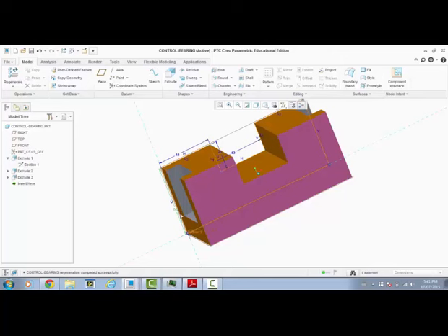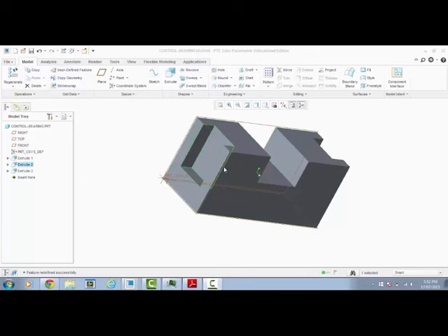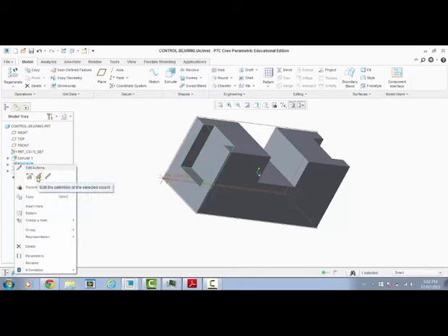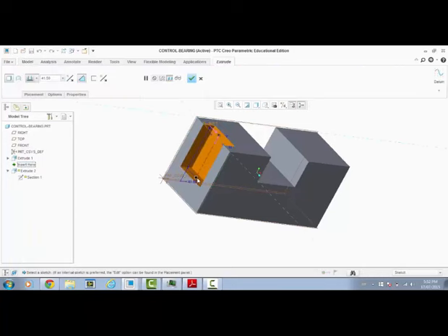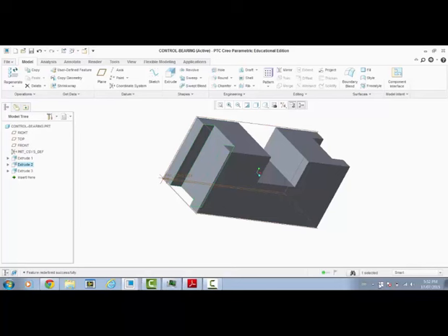It automatically changes it. Only problem is now we've got other things to change. So now we have to change the extrusions at both ends. We'll go over to extrude number 2. Now we're going to use the right mouse button, click, press the edit and definition, change this, pulling it down. We're going to change it to 60. Press enter. Click the button.